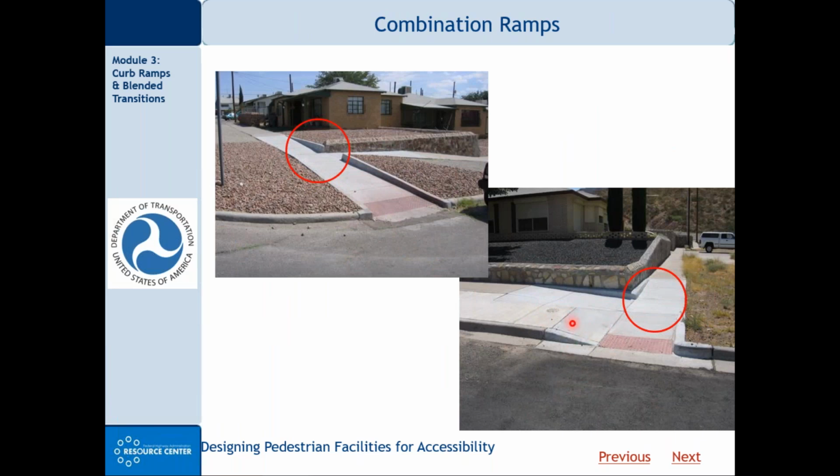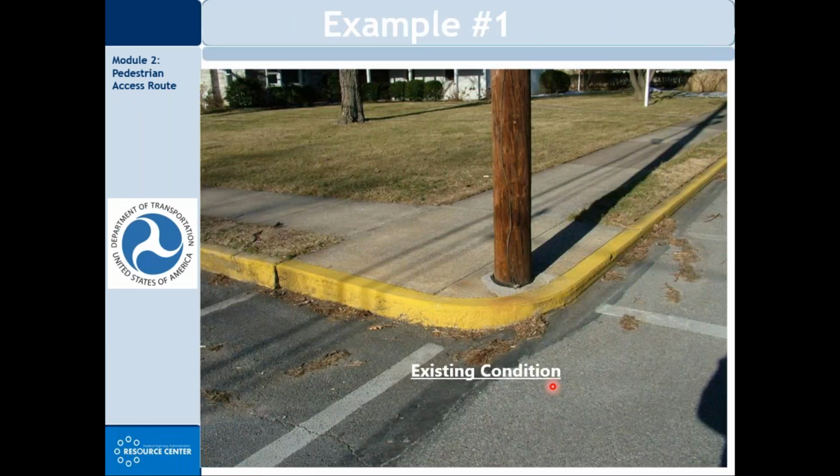This is here for the safety. That flare is there for the safety of able-bodied pedestrians. And one concern with steep flares is what happens if you get snow and ice on that flare, like Columbus or Morgantown or Cleveland. But here in Phoenix, probably don't often get snow and ice on that flare, so that's probably not a real big concern given this specific context.